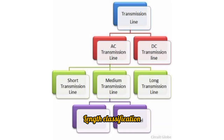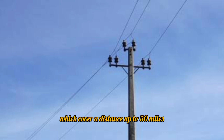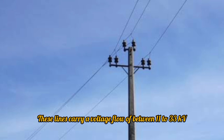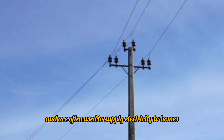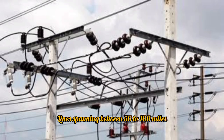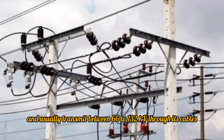Length classification. Short power lines are those which cover a distance up to 50 miles, 80 kilometers. These lines carry a voltage flow of between 11 to 33 kV and are often used to supply electricity to homes and other low-demand power networks. Medium lines. Lines spanning between 50 to 100 miles, 80 to 160 km, are classified as medium power lines and usually transmit between 66 to 132 kV through their cables.